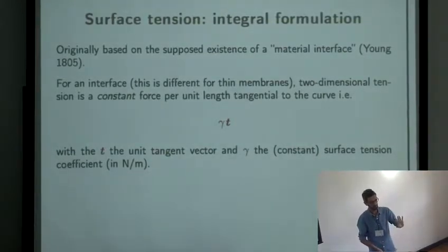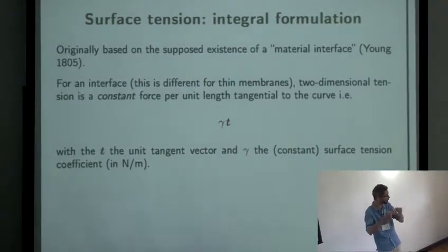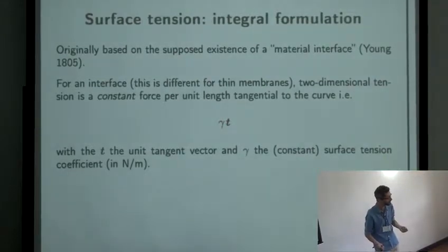And they are really interesting papers for two reasons. The first reason is that they show two different understandings of what surface tension is. You look at a flow with surface tension and there seems to be something there, right? There seems to be a film sitting between the air and the water. So for a long time people said, oh, there is a material interface, a real film sitting between these two things. What is this film? It's a weird thing, right? That was essentially Young's version of it. So what you have here is a geometric interpretation of this film sitting between these two surfaces.